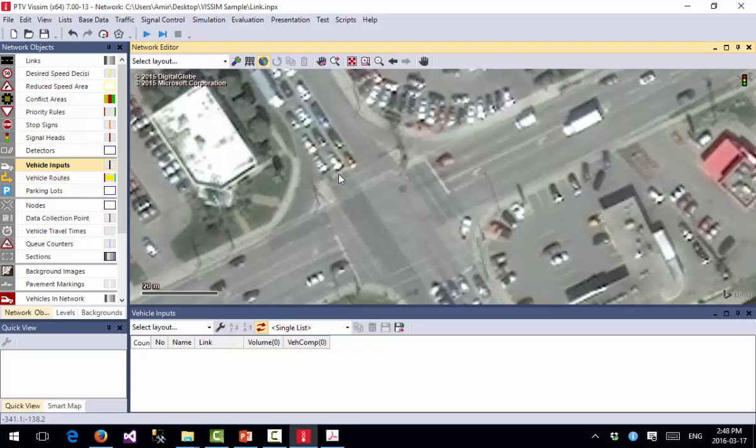For the other direction here, I will assume maybe 2,500 vehicles per hour, maybe 20% right turn, and then maybe 10% right turn. Does that look fine to you? I think these values are reasonable. Normally this is true. Then we will model this and see how it works.